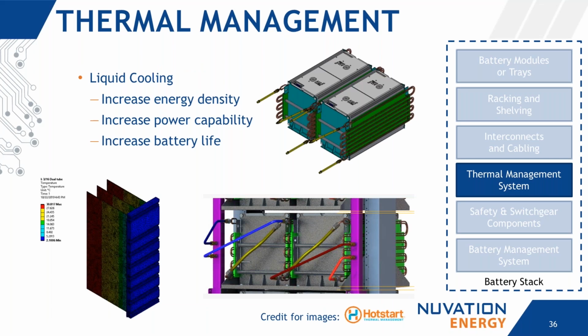Some of the benefits seen with liquid cooling systems are the ability to increase the energy density of the system, an increase in power capability, and an increase in battery life. This is because with a liquid cooling system, you can get the cooling medium much closer to the source and exchange the heat quicker. So while there may be more upfront cost to a liquid cooling solution, it can lead to long-term savings in some applications.